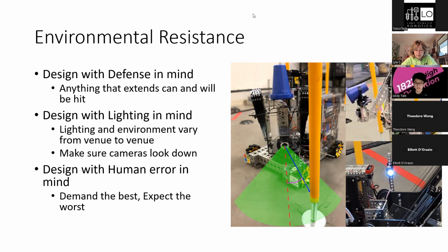So I guess the way we overcome these integration issues is, before we even start designing, we set very clear boundaries for each module about how they're going to interact with each other. And of course, what kind of space they're going to take up on the robot and how many motors or servos they can use. Does that answer your question?